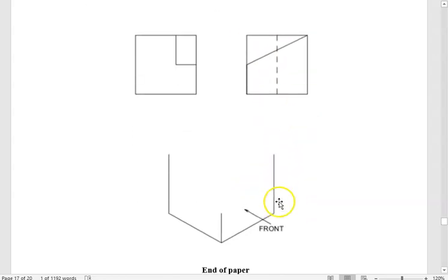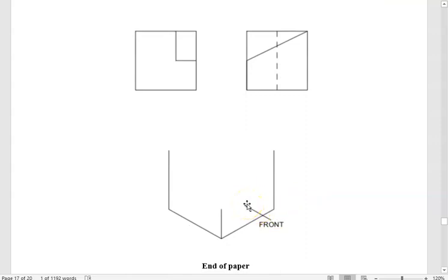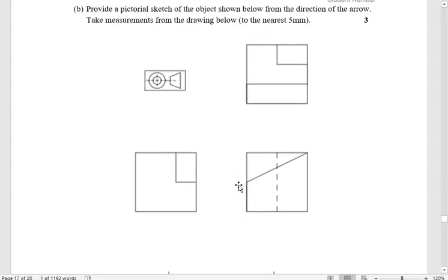So this here is the front view. I had one student who drew it the wrong way, but he told me in the exam that he'd drawn the wrong thing, so I took it into account. I had one other student, and this is the first time I've used this exam, so at least 50 people have seen this, and only one person's caught that this hidden detail line indicates that this shape, this hollow, goes all the way through, but the top view shows that there's something down here. There's some sort of object happening down here.